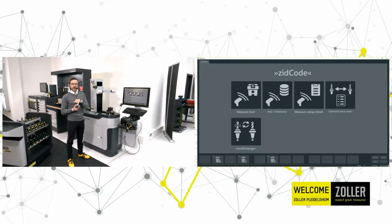You can get a printer from Zoller for printing them out and easily sticking them on the tool holder. You can also laser mark this, but laser marks are forever. So if you need to change something, you cannot change it because it was laser marked already. And if the groove of the laser gets dirty, the scanner cannot read it. So this label is also better for reading.